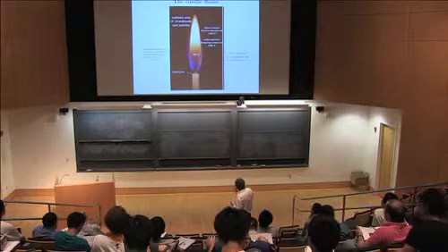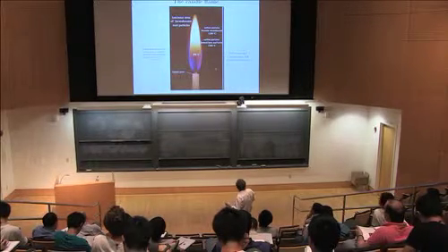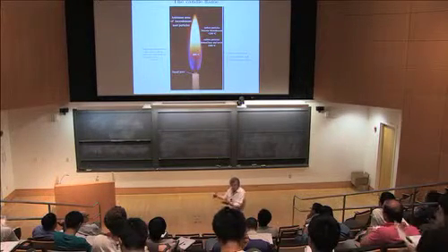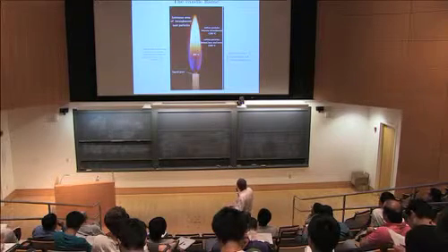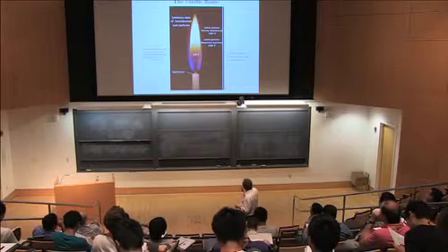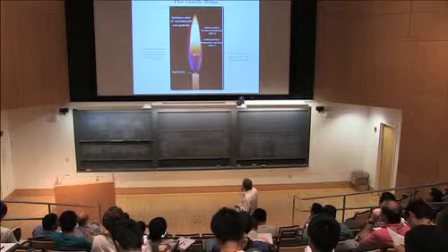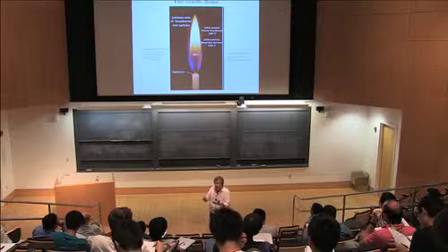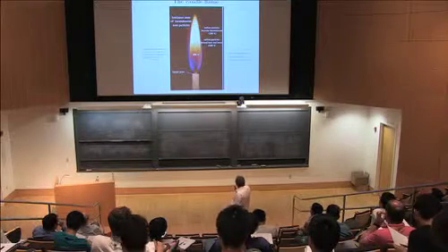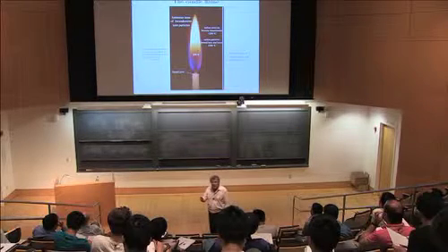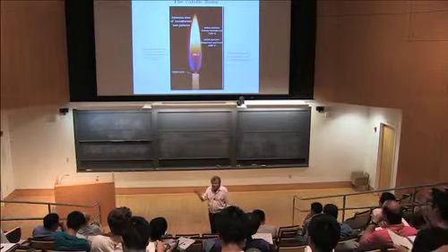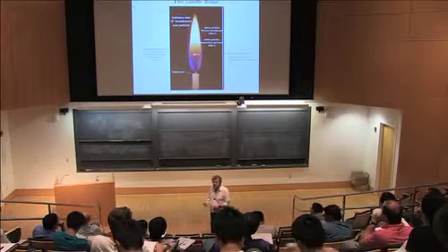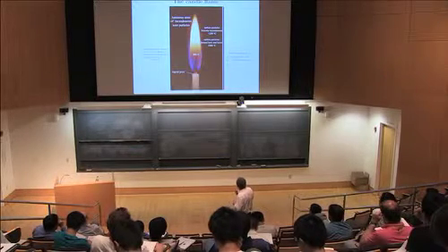Essentially, what is important here is that you need oxygen entrainment to reach the surface where the fuel has evaporated and diffused, in order for the two to meet, mix and react. And since the primary mechanism is diffusion, the flame of this non-premixed system is usually referred to as a diffusion flame. And we are going to see that later again.